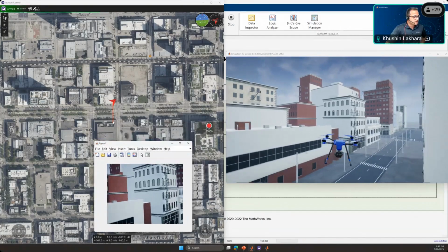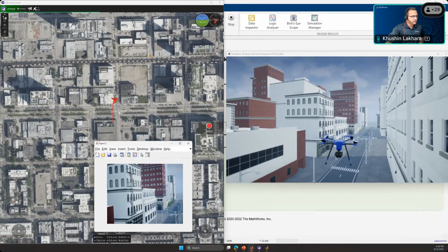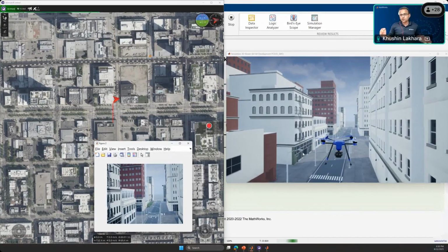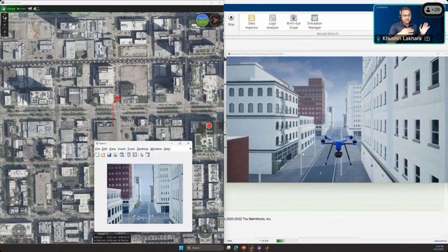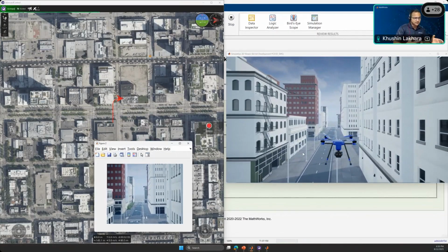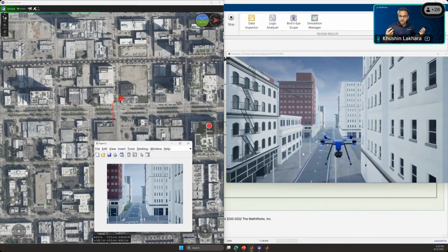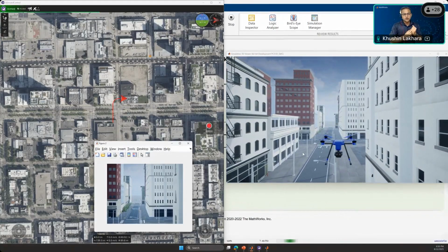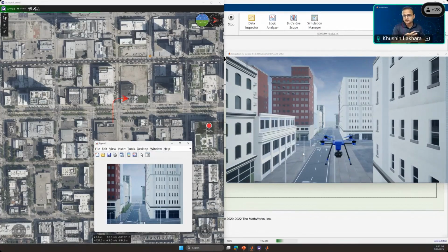Now you can see that in the QGC, my ground control station, my vehicle is continuously moving and it has taken a turn as well, right? And that's how you can plan your mission with QGC and implement it using Simulink and do the photorealistic visualization. You can get the pictures here from your camera, and from the camera you collect all these pictures and feed them for your neural network or your image processing or your computer vision system training.